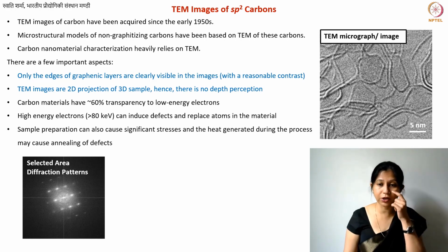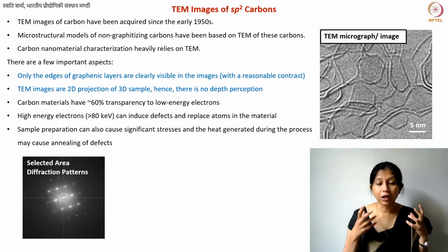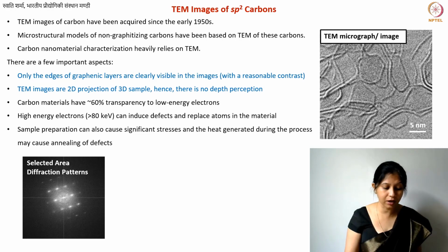It is very, very difficult to get this kind of information, and diffraction patterns can often be misleading. If you try to analyze this particular diffraction pattern, it's very difficult to get any information, because even when you have pure graphite, you do not have hexagonal close packing. You have a hexagonal structure but not close packing, and all of these rules which allow you to find the potential crystal structure are for well-defined crystal structures. They are for HCP in this case, and our material is not HCP. So don't get too confused by the diffraction patterns. That is what I'm trying to say.